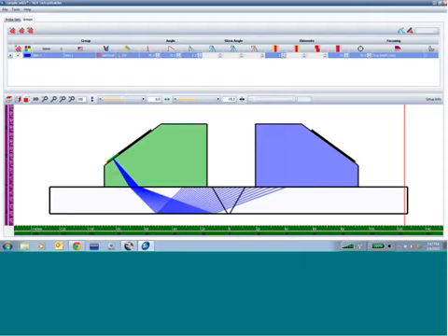Now, we have 4 areas that we have to cover and 4 areas that we have to cover properly. I want to make sure that I'm putting purpose to these beams and that they're actually being used for something specific rather than just making sure that there's coverage. Normally the way I start this process is I start with the bevel because that's the area that's more tied to those particular angles.